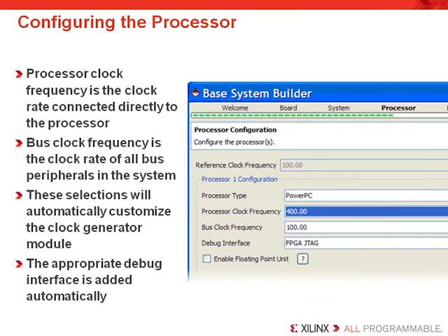Depending on your processor, you'll then be asked to configure the processor. One of the most important options is the clock frequency that you plan to connect the processor to. The GUI will allow you to specify a different processor and bus frequency if you're targeting the PowerPC 440. But don't forget that the requirements for your bus frequency are dependent on the PLB v46 bus standard.